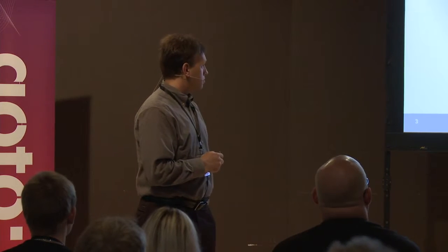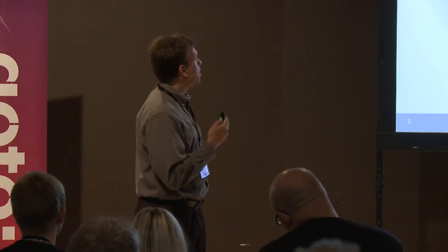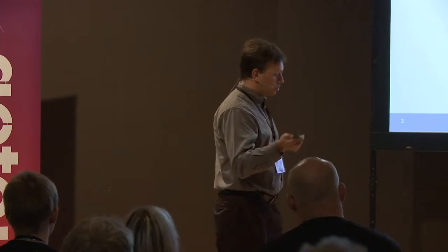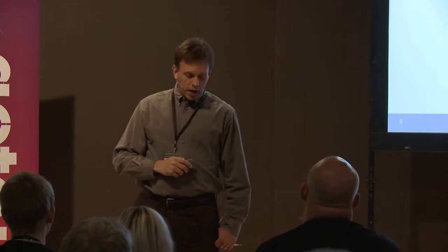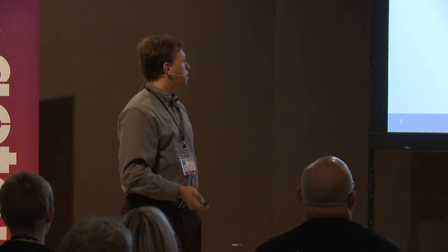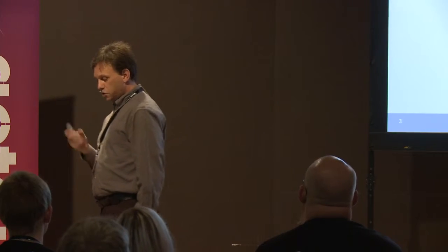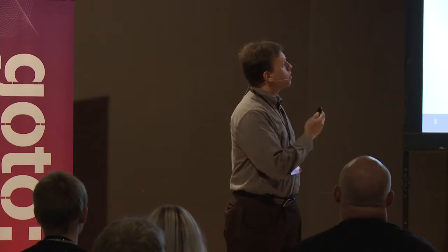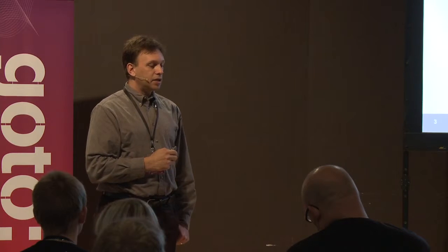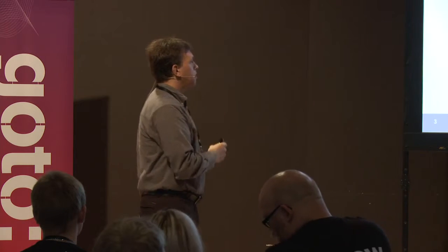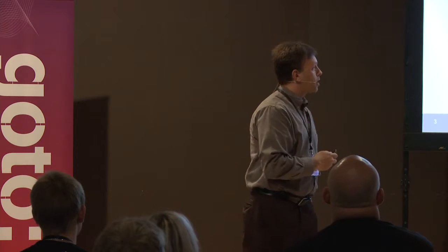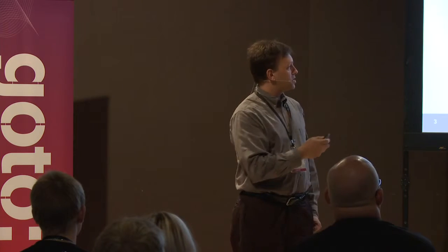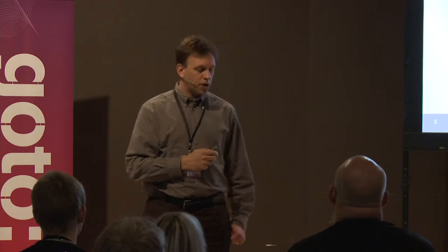So GPUs are a fairly radical solution then perhaps for you, but if you want to get even more radical than a GPU, in the world where we have very hard power constraints and difficulties with scaling, you can actually design your own hardware. If you actually want to design your own ASIC, your own chip, you need a lot of money and a lot of time and a lot of expertise. FPGAs are field programmable gate arrays. This is basically programmable hardware, where you can create a hardware design and dynamically load it onto a chip. And effectively, it's a lower entry barrier to design your own hardware, and it doesn't run as fast, and it's not as dense as a custom ASIC, but it is a way to quickly prototype hardware.